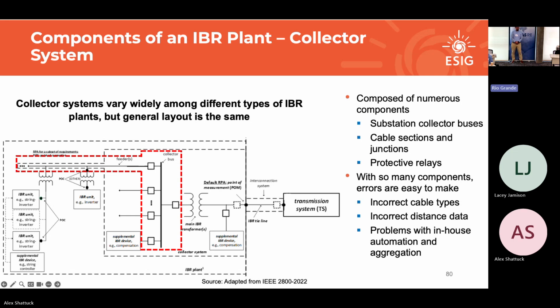And this is where we talk about how much level of detail you want to put in here. Do you need a full frequency representation of a short cable in a feeder? Maybe, depending on the study. It's something to keep in mind in general when modeling all these sections. A lot of the time, especially if it's an aggregated model, you're using a pi section. But outside of the simulation, this is another place, especially the main power transformers, where it's really easy to mess up.